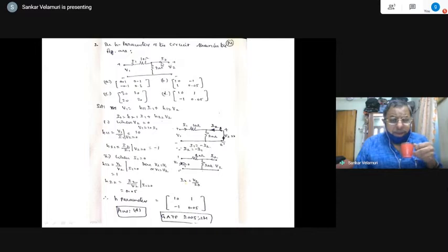So you have to understand that here the resistance value is shown to be 0. That needs to be considered in the parameters because it is a T network that is being considered. So I am taking a cup of tea and explaining the T network for finding the hybrid parameters. The corresponding resistance is given as implied, to be taken as 0. That is the meaning of this. Because of that, you will get a short circuit here. Otherwise, these two elements would have been parallel. Even if you make it parallel, 20 into 0 by 20 plus 0 is 0 because the multiplication is 0. So H11 is equal to V1 by I1, which is 10, right?